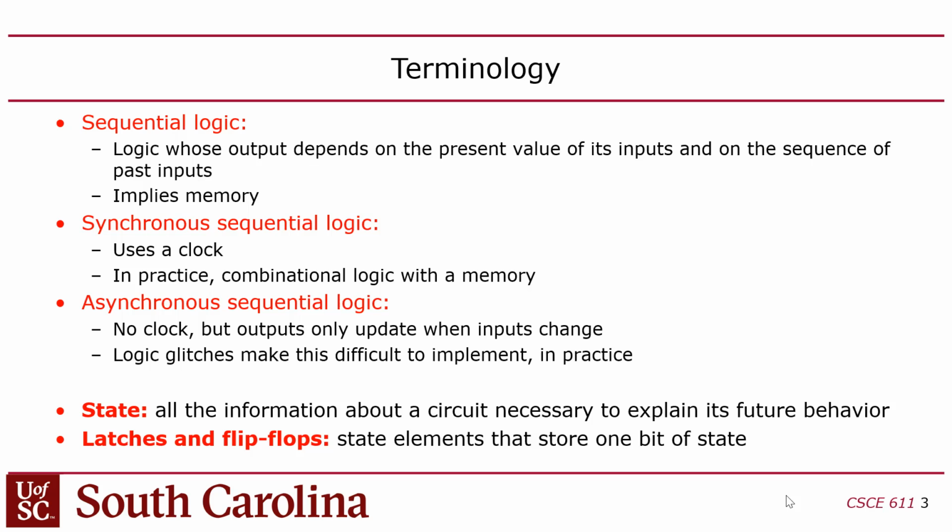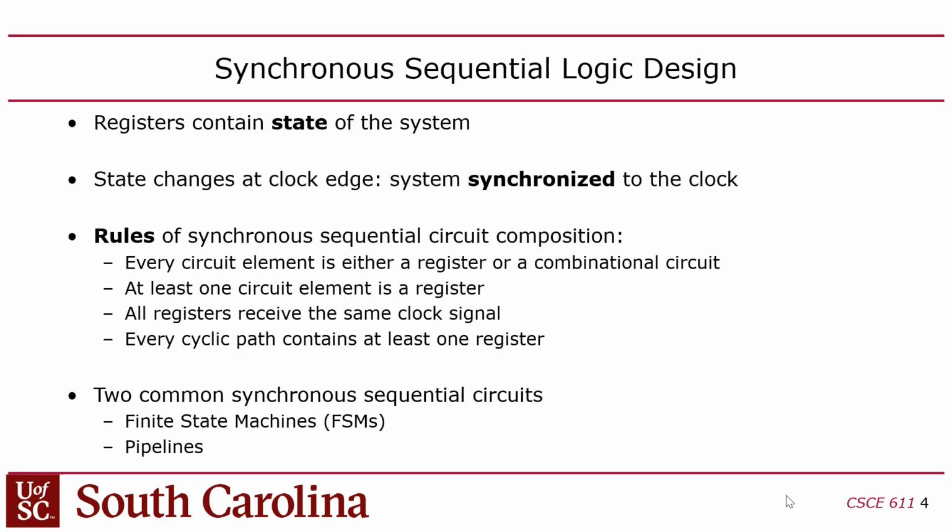And of course, the difference there is latches are level sensitive, so they're active whenever the clock is at a certain level, high or low, whereas flip-flops are edge sensitive. Those are the ones that we're using in the class. I talked a little bit previously about the difference between how latches and flip-flops work.